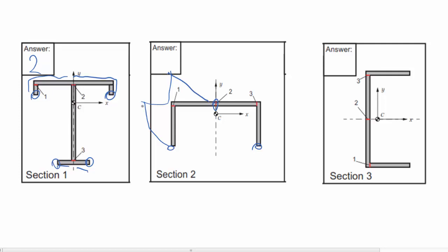This means that if we look at the location just beyond the corner, the location that is placed horizontally on the vertical member will have a higher shear stress, since due to the quadratic decline, the shear stress is slightly higher on that side of the corner. So, point 1 has the highest shear stress.